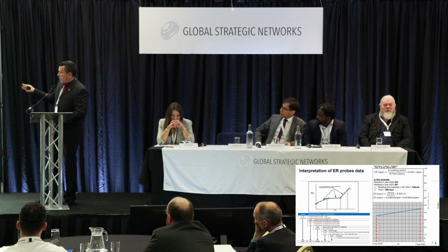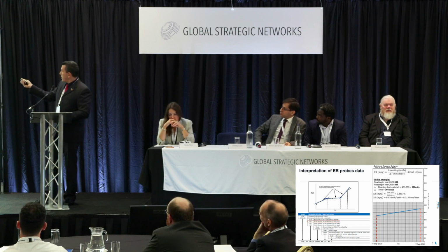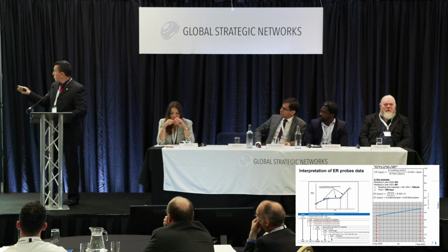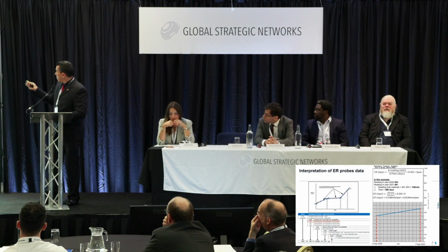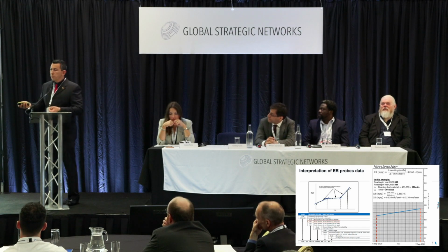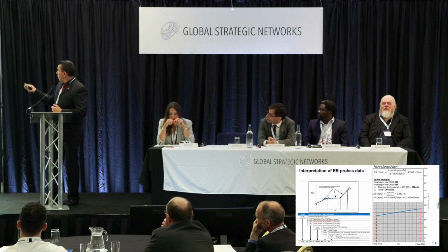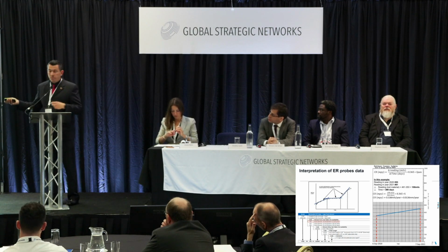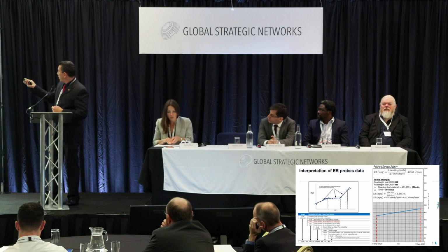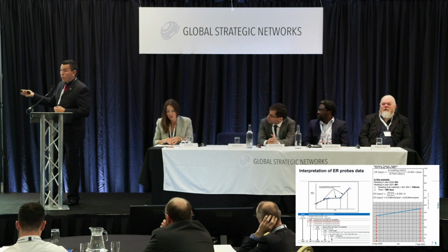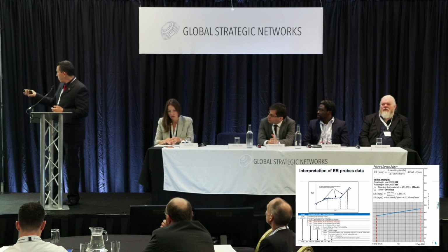Then you can use the equation that is provided by the supplier of the probe, depending on the span, meaning the accuracy of the probe, if it's thick or thin. You will use a calibrating factor. And when you combine the difference between at least 2 readings, the time, and the specific characteristic of the probe, you can get corrosion rate in millimeters per year, for example.